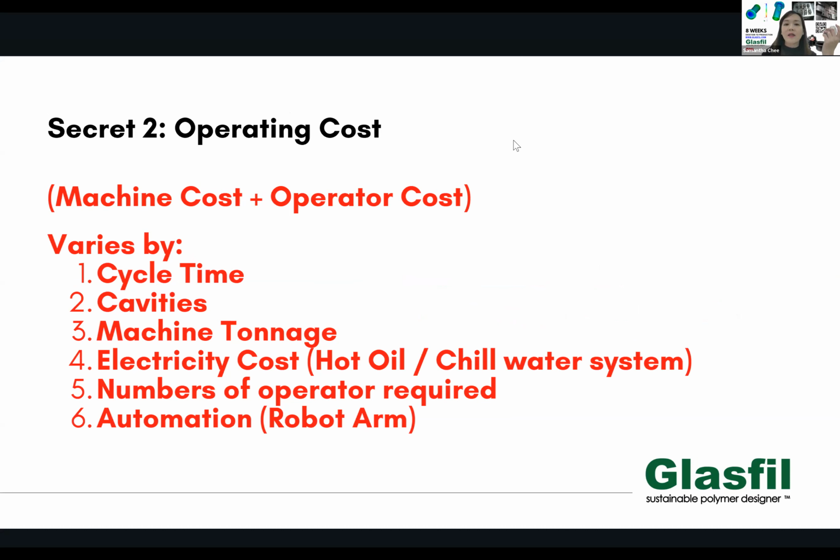Typically cycle time ranges from around 20 seconds if you're doing normal injection molding. If you're using fast injection molding, sometimes it can go as low as 8 seconds. Food packaging, like takeaway packaging, can typically be 8 seconds because it uses fast injection molding. Other parts can go up to 80 seconds, depending on what part you're talking about. So it has different cycle times.